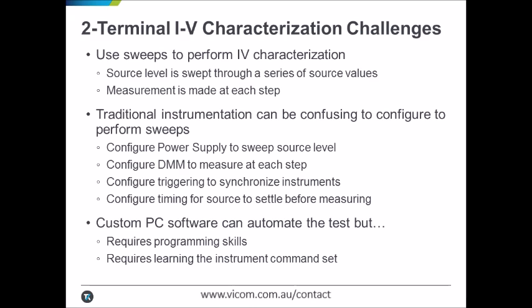Performing sweeps with traditional instruments like power supplies and DMMs can be quite confusing for first-time users and even experienced users alike. To perform a sweep with these instruments, the power supply must be set up to output a series of voltages and the DMM configured to measure the resulting current.